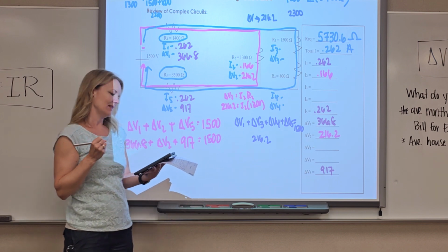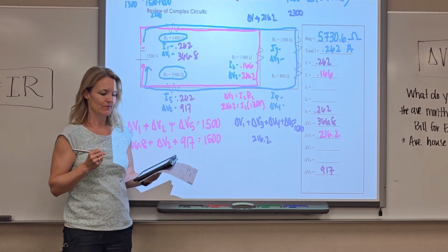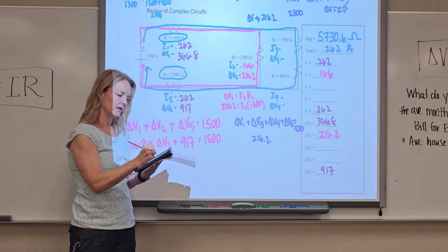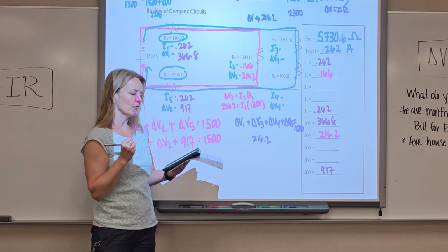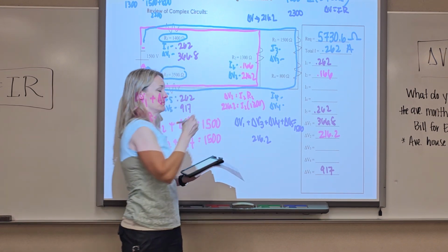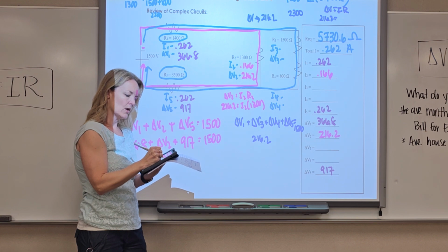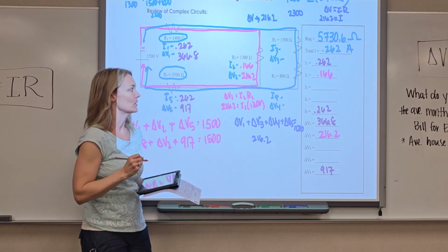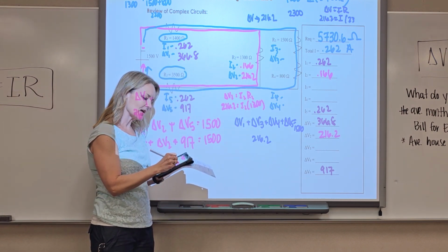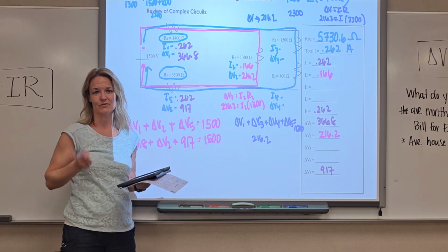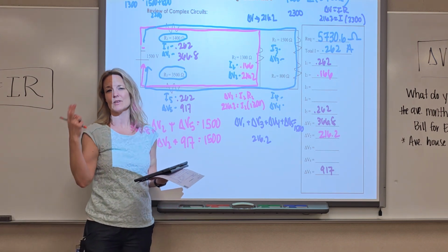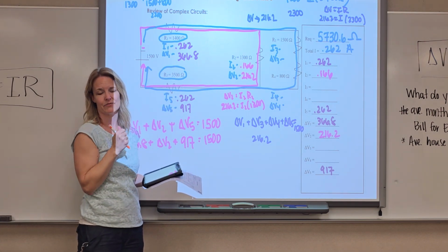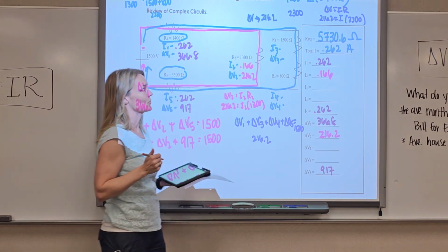And we are going to set that resistance. We're going to use delta V equals I times R. We're going to take the voltage that's left to go through both of them, 216.2. We're going to find the current that goes through both of them, because what goes through one has to go through the other. There's no other choices. And for the second time, we are going to use the resistance of the two of them together. Both times you use their resistances, you have to add them together. Once at the beginning to find the total resistance, and once now to find the total current.